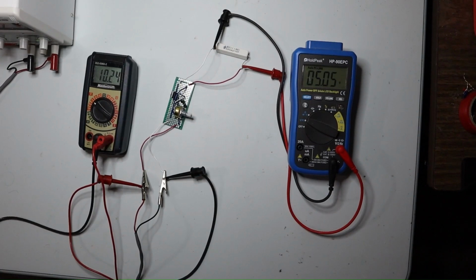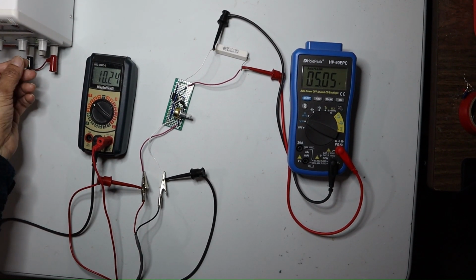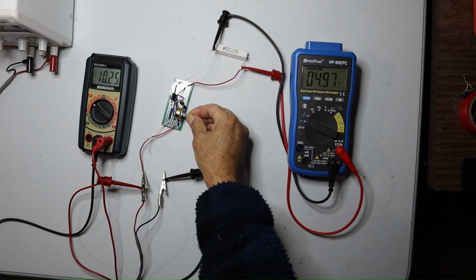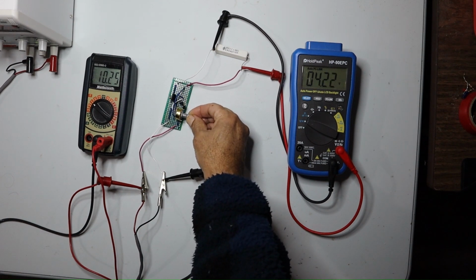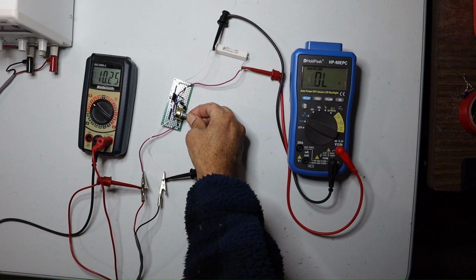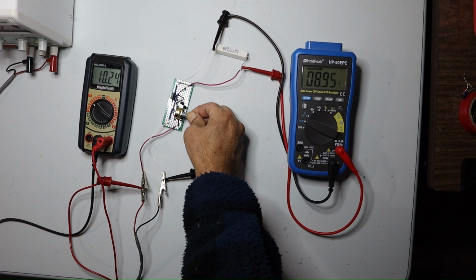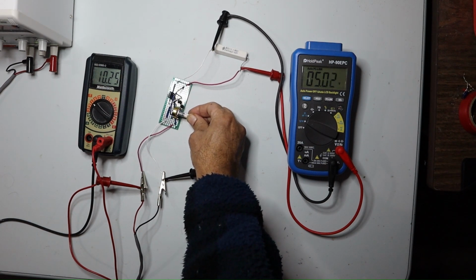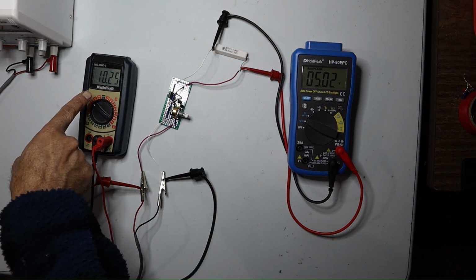So now this is the regulated power supply, and I am using an input voltage around 10 volt and the output voltage I can vary with this potentiometer. A 47 ohm load is connected at the output. You can see as the potentiometer is changed, the output voltage is changing, and I wish to keep it at 5 volt. The output voltage is going up, and then I'll take it down to 5 volt. So almost at 5 volt, and input voltage is 10.25.